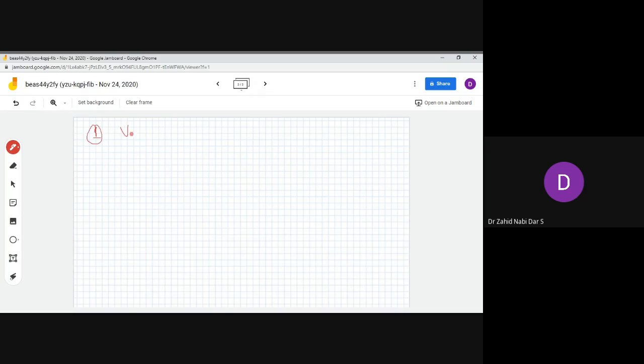So see here, Vp by Vs is equal to Np. Instead of Np, I'll write Tp by Ts is equal to Is by Ip is equal to, let's say A. Some books will write K, whatever it is. So here if I want the value of Ip, I have to write it in terms of Vp by Rp. Voltage by resistance would be my current. Is would be equal to A times Ip.